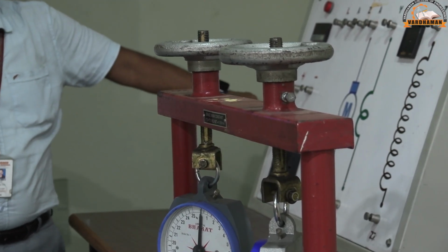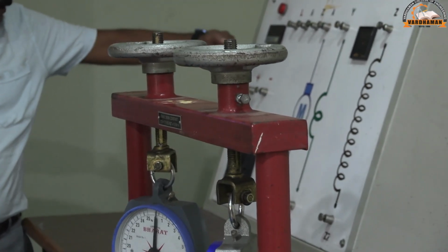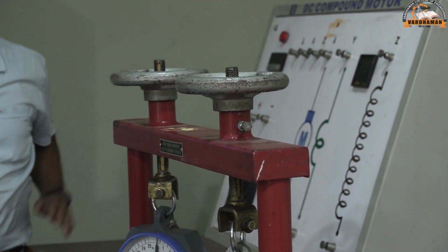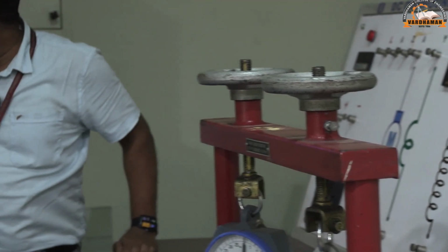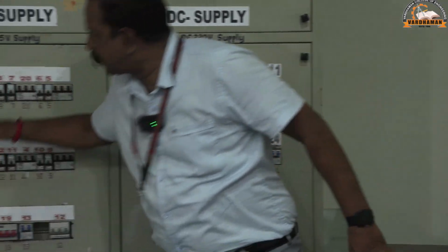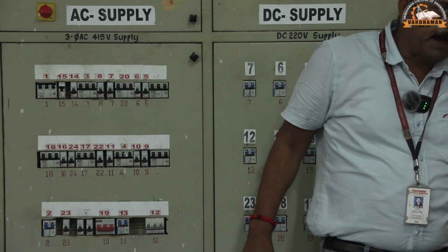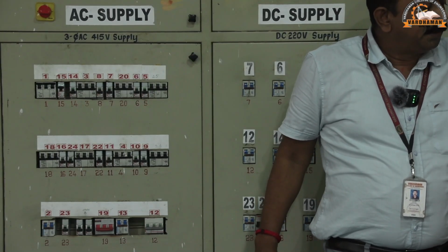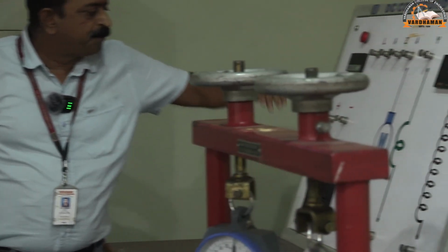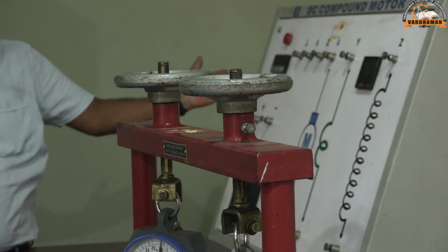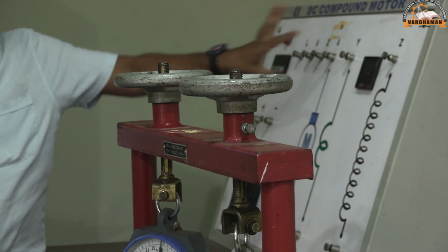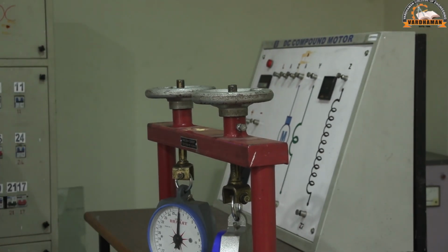If you push this button, that current is connected to the terminals. These are the sections. The first section is the mains, the second section is the MCB, the third section is the control panel MCB, and the fourth section is through fuse protection. It is connected to terminals. From these terminals, the motor is going to connect. So this is about AC.